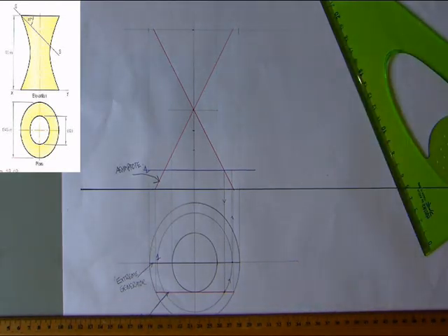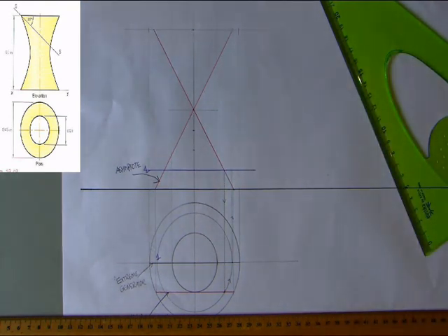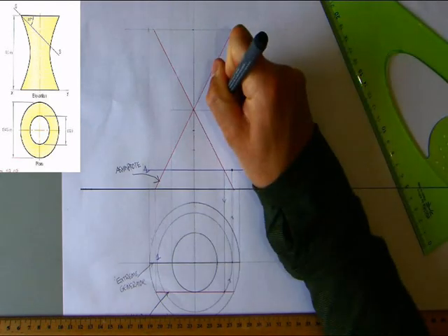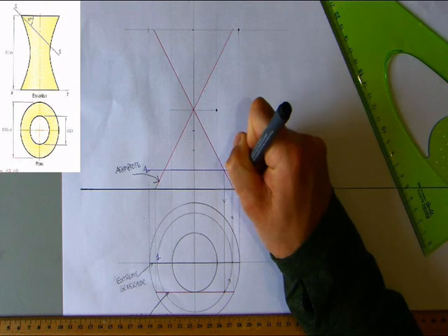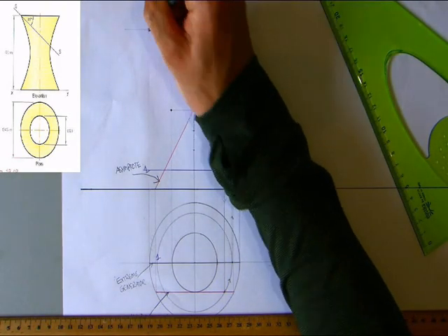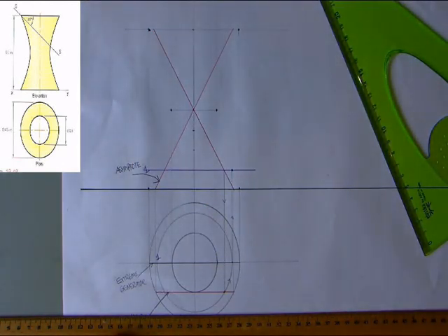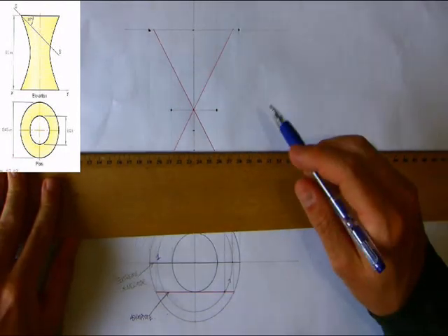Alright, so we're going to bring that up here to this height, and that is then a known location on our hyperbola. We already knew 1, 2 and 3, and the same on the other side, 1, 2 and 3, and what we need to find is points in between those, because it's too large of a gap to randomly sketch. Okay, so now we're going to do the same principle for cut number 2. We're going to take cut number 2.